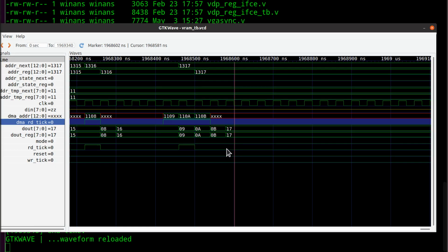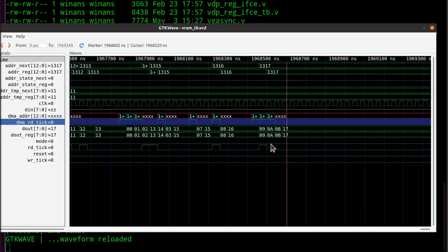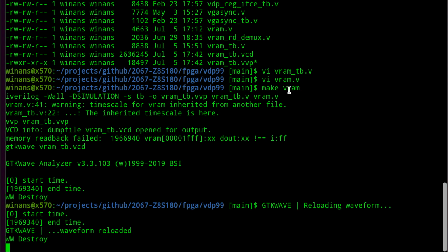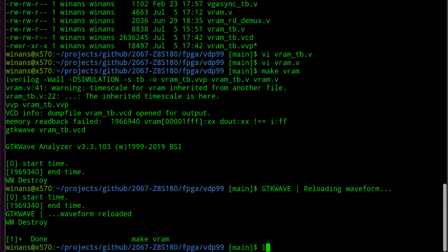Okay, and it turns out that, again, the Z80 cannot do 2 input instructions this close together. Because remember, this is a 25 megahertz clock, and even the Z80 that has faster compressed instructions over the old original Z80, they still take several more than 3 clock periods to do an input operation or an output operation. So this is practical, useful, and that's why I built it this way. And we'll see how this gets used as we move forward. But I wanted to make sure everybody gets a good understanding of that. Otherwise, not very long, but somewhat subtle code.